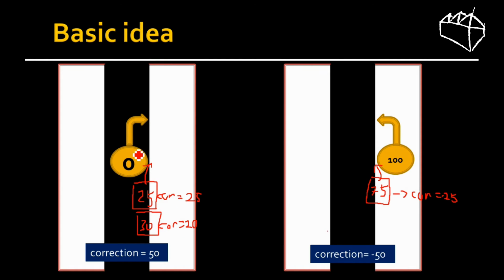And the distance from your color sensor to the edge of the line is called the error. So error equals the distance between your actual position and the offset. So here this edge of the line is called the offset, where you want to go.